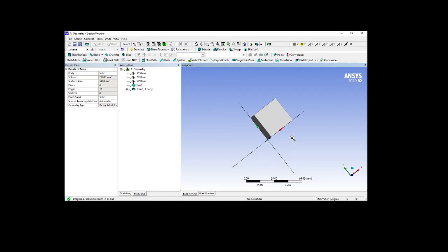Next, if you press the control button and the middle button, then it will turn into a pan movement. If you want to zoom, just rotate your middle wheel. This is how you can perform the three operations with your mouse without activating all these buttons.